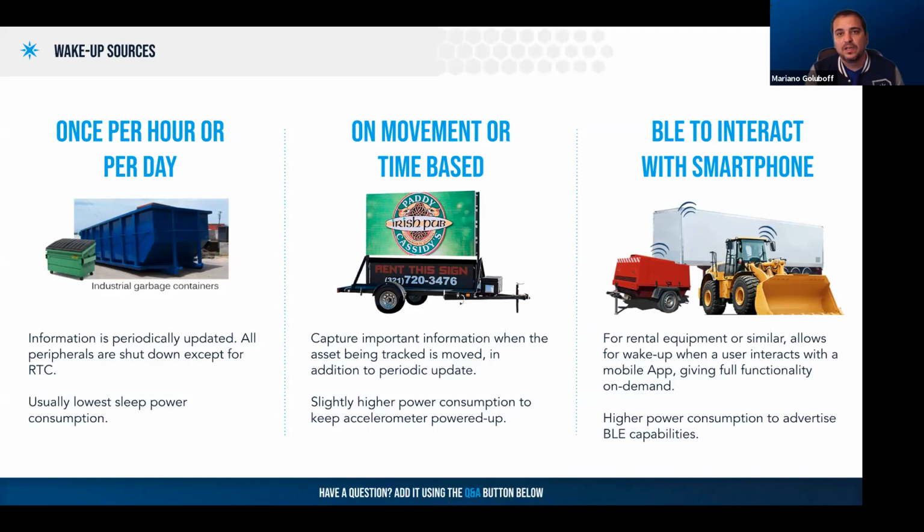In the middle, we see an application that also wakes up based on time, but it will also need to wake up if the device is moved. This can be accomplished with a tracker that has a built-in accelerometer. For this use case, you will need a sleep mode that keeps the accelerometer as well as the real-time clock powered on. So it will use slightly more power than the real-time clock only.